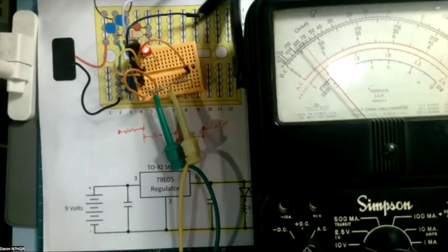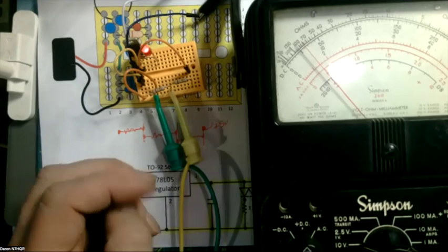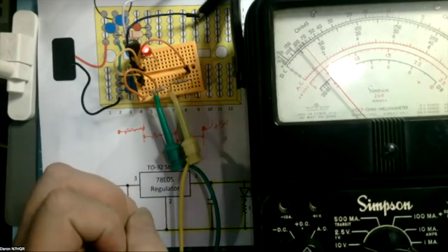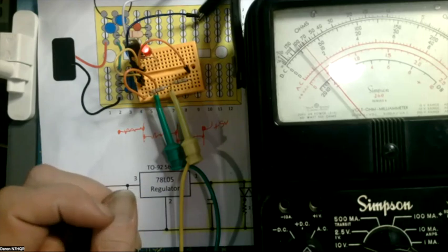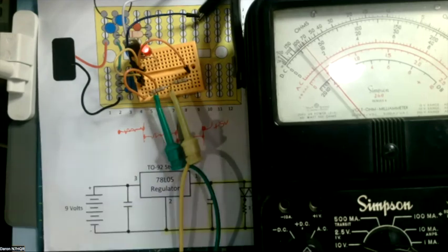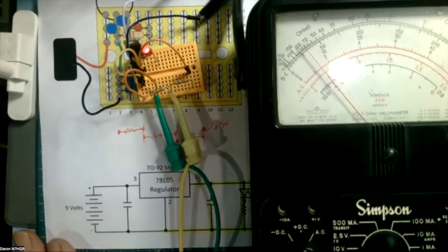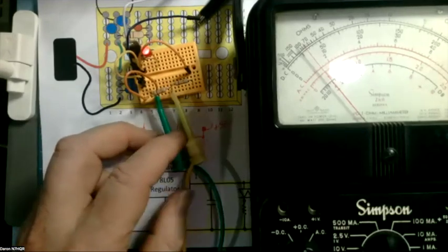So when you're talking about voltage dividers, here's another thing that you need to be aware of. Fortunately, most of us have digital voltmeters, and they have 10 million ohms input. And most of our oscilloscopes have 10 million ohms input, like Darren's little one that he showed us. Although if you use it with a times 1 probe, then it'll be 1 megohm input, and that would change the voltage. Very good point.